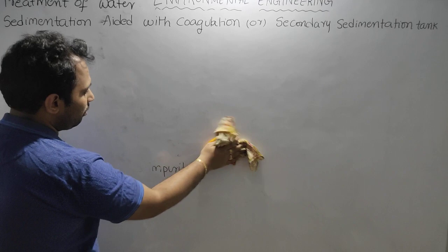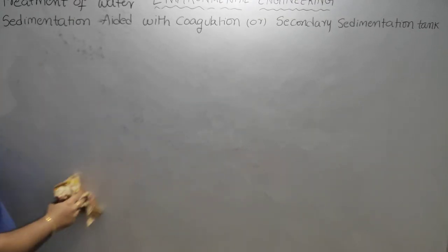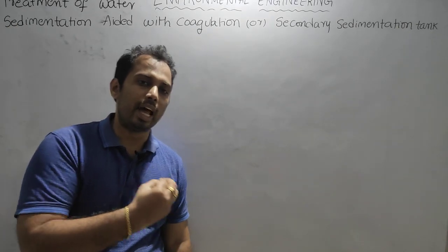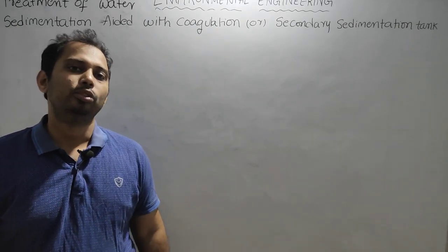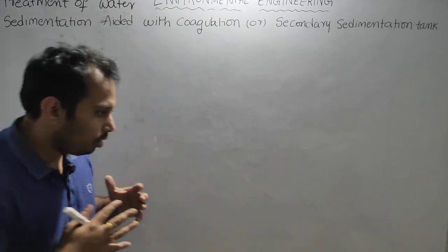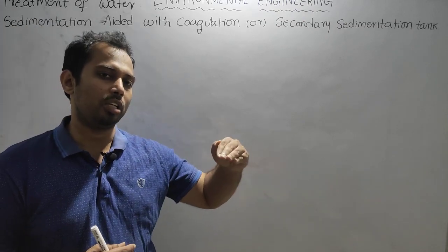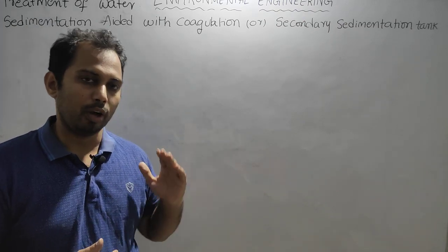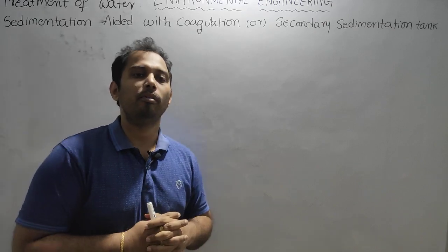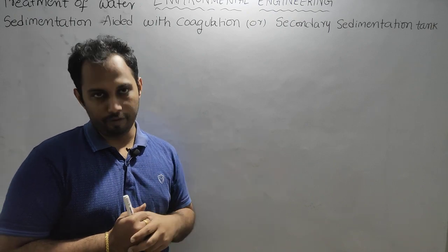All the finer particles can be removed by surface forces, not by body forces, because these finer particles during their travel in the sedimentation tank will get wear and tear. That means they have to travel through the water, and because of the friction in the movement, they generally carry a negative charge on their surfaces.